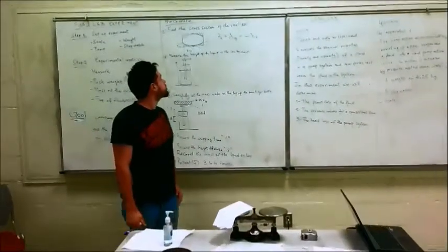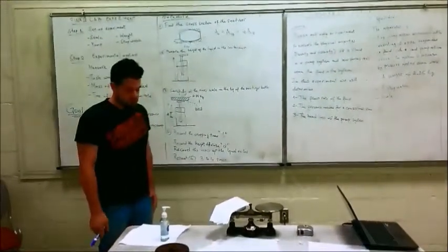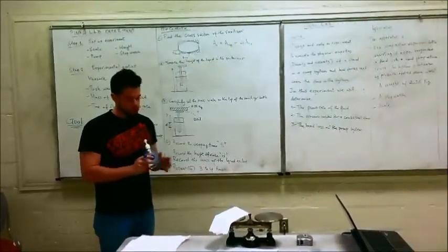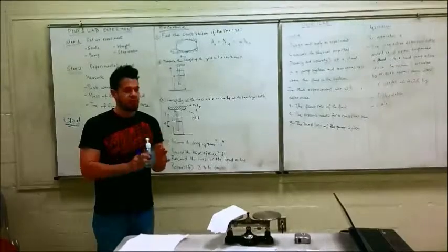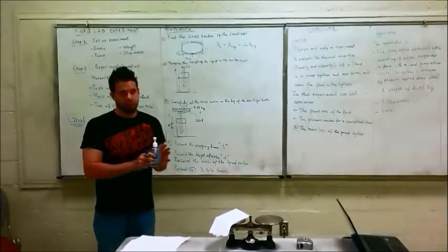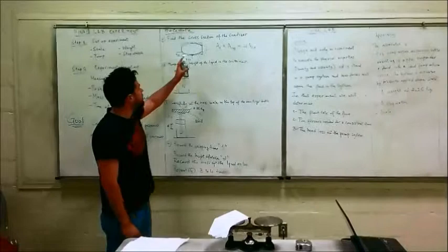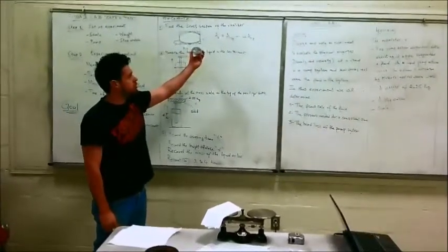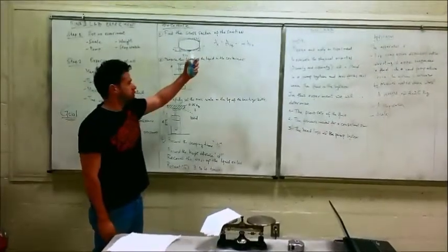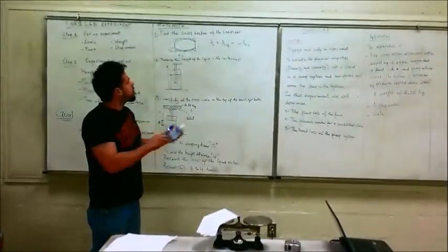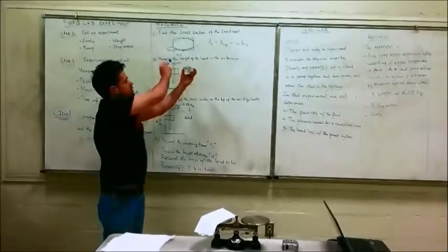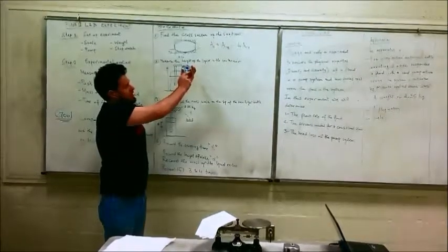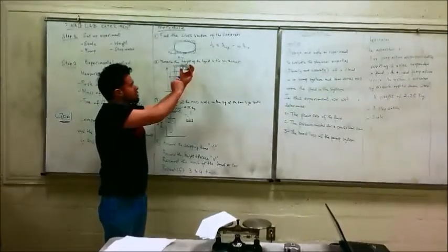Now, for the procedure itself, first thing we need to do is determine the cross-sectional area, or rather, we need to consider the volume that is expelled during each pump. How we will do this is we will measure the cross-sectional area of the storage tank for the pump system, which is the bottle down here. We will take an outline of a square, illustrated here. Now, because this is round, it's very difficult for us to find the exact cross-sectional area. So this is largely a square.